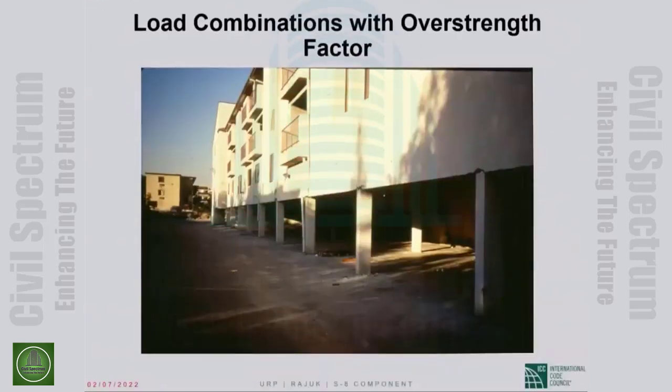these are very, very common around the world, actually. Many parts of the world, the residents of apartment buildings park their cars underneath the building. So the lowest level is open, supported by columns. But then from the next level, you have shear walls, because those are residential units and walls are needed to separate the different spaces, bedrooms and so forth.